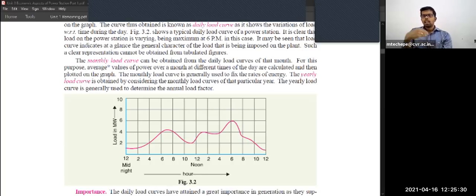So based on the season, today is falling under the summer season, and in summer the load might increase over the previous year. The previous year's summer was 13,200 megawatt, so this year also around 13,500 megawatt. So we are generating 300 megawatt more like that. That is how we can predict the load, and even hourly we can predict.